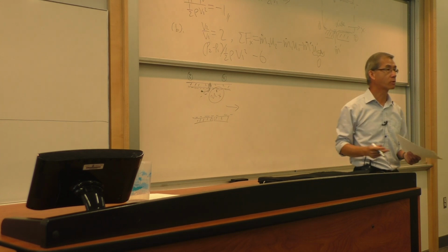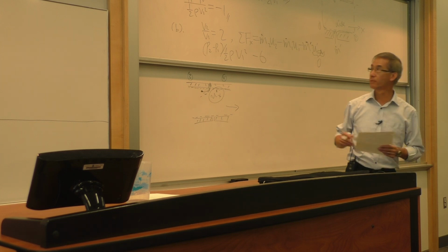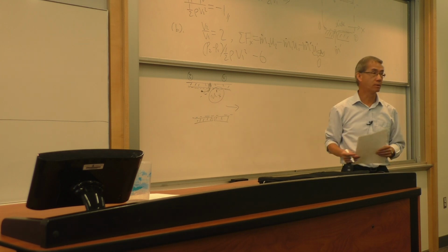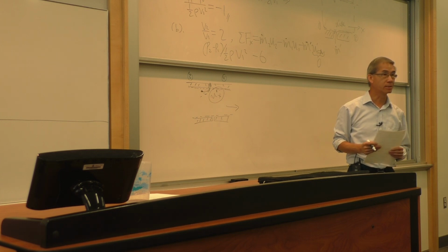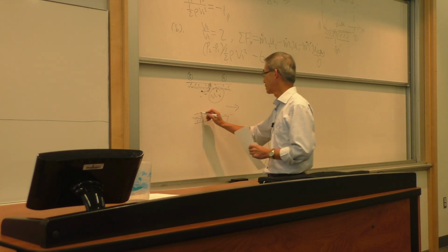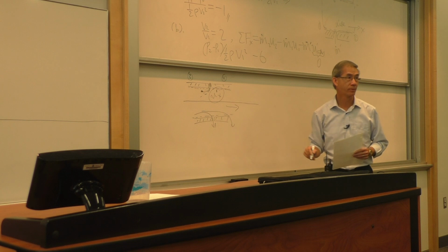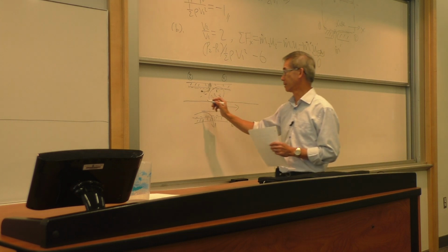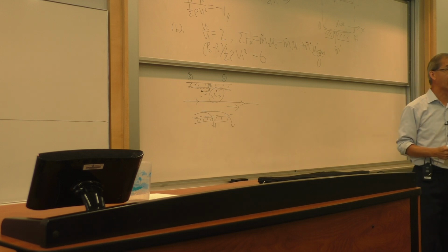It is something I don't know, because there's not enough information given in the problem statement for me to estimate. So the use of momentum will give you the wrong answer, because you have neglected a certain part of the x momentum in your formulation. And that's why in the hints, I asked you, besides the withdrawal of the fluid due to suction, can you still follow a center streamline that is almost undisturbed? And there's no turbulent mixing, so that Bernoulli can be used. And that's how you calculate the last pressure drop from 3 to 4.